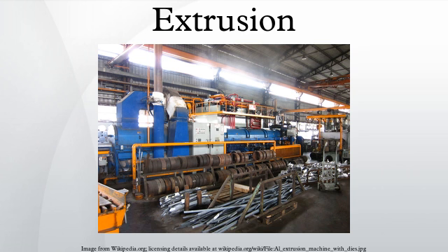In 1950, Eugène Séjournet, of France, invented a process which uses glass as a lubricant for extruding steel. The Séjournet process is now used for other materials that have melting temperatures higher than steel or that require a narrow range of temperatures to extrude. The process starts by heating the materials to the extruding temperature and then rolling it in glass powder.